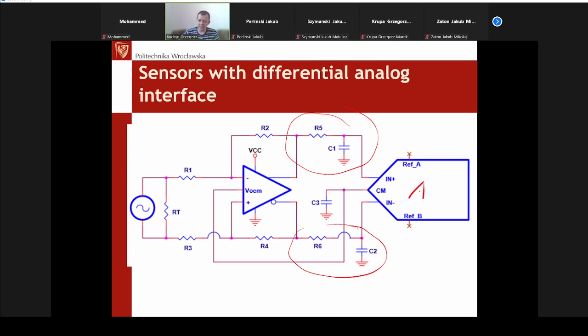This is a kind of important element because the ADCs, especially in the microcontrollers that we have now, tend to have very nice and very fine resolution. Quite often we talk about 12-bit, and more often 16-bit ADCs with pretty decent bandwidth, about 2, 3, 4 megahertz sometimes, which from one perspective is